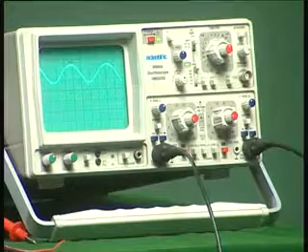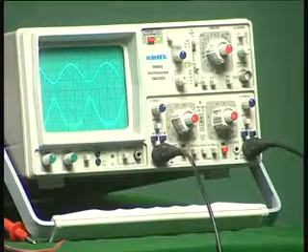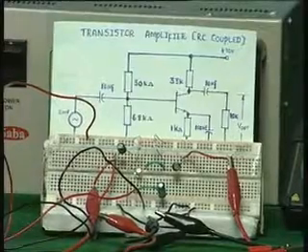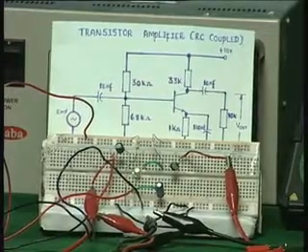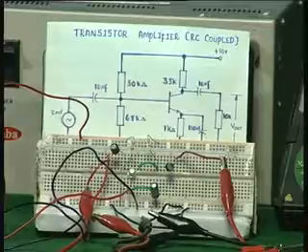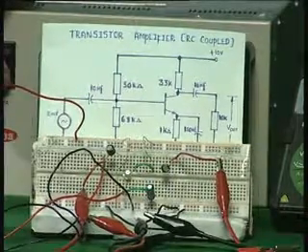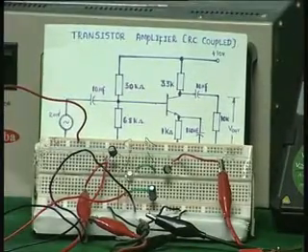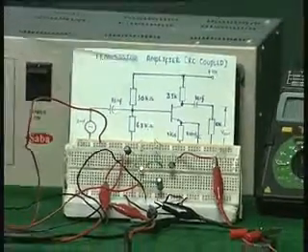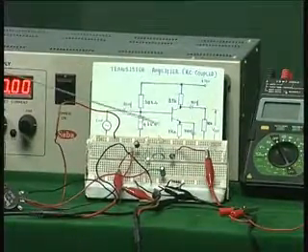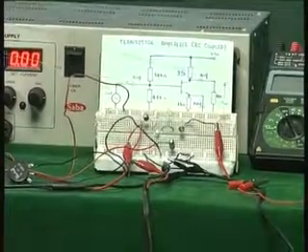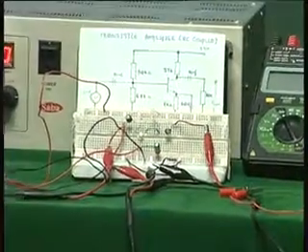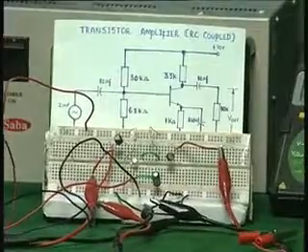So I just want to indicate to you that the choice of the various resistors, especially that RE, which is the biasing resistor, is very important in choosing the performance of the amplifier. So you do get amplification gain, even though we have not actually calculated what the gain should be in this case, but we do get enough amplification. So you can see the biasing circuit is very important. After that you have to use coupling capacitors, and this is the bypass capacitor. Once you do that, what you get is an RC coupled amplifier of one single stage.